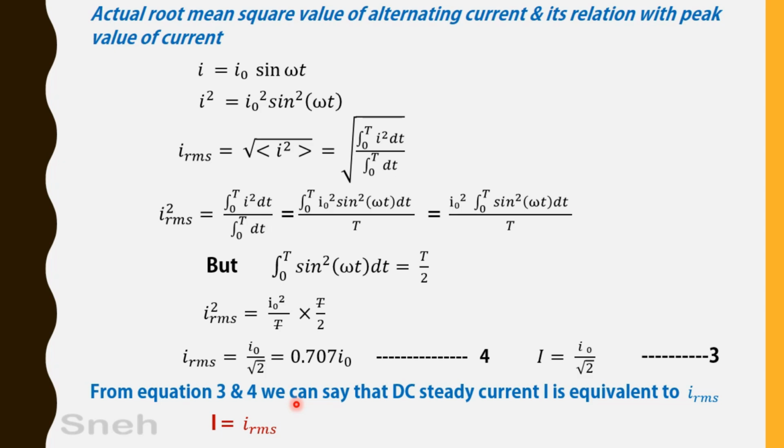Now, here, we have seen this RMS value, as well as the average value, and we have discussed instantaneous values. Instantaneous value is the value at a particular instant. Average value we have taken over the complete cycle, it is 0. Even we have taken it for half cycle. For half cycle it is 0.637 times the peak value, and IRMS value is 0.707 times the peak value.